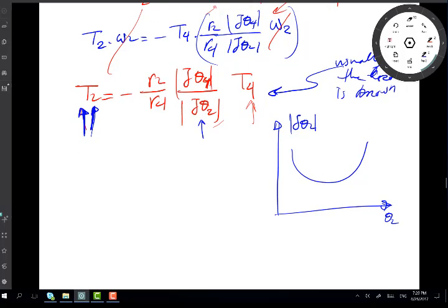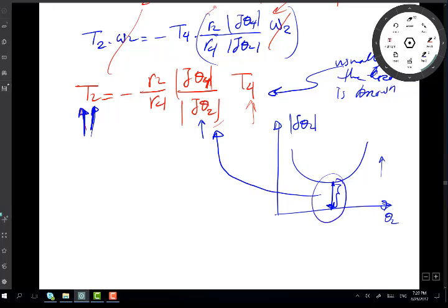But even if it stays all in the positive, which is great, or all in the negative, which is also great, I want to make sure the minimum value is still large enough, because this goes into T2. If this minimum value is close to 0, then at this specific point my torque T2 is going to be high. So the motor and the flywheel and everything on the crank will struggle to provide this torque. When you hear a linkage like this running, you can hear the noise. You can tell everything is suffering to make it go, just because this determinant was close to 0 at some point.